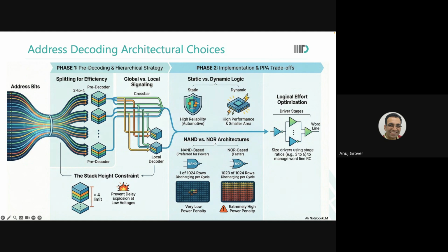I have it down with the NAND and NOR. So are we using this in the pre-decoding or post-decoding? Wherever you choose, you have this option everywhere. In the figure that you've shown, we are using both NAND and NOR in the pre-decoder. When you are designing the pre-decoder, do you not have a choice to choose between NAND and NOR? There also you have a choice. If I'm using NAND, then pre and post both will be NAND? No, not necessary.